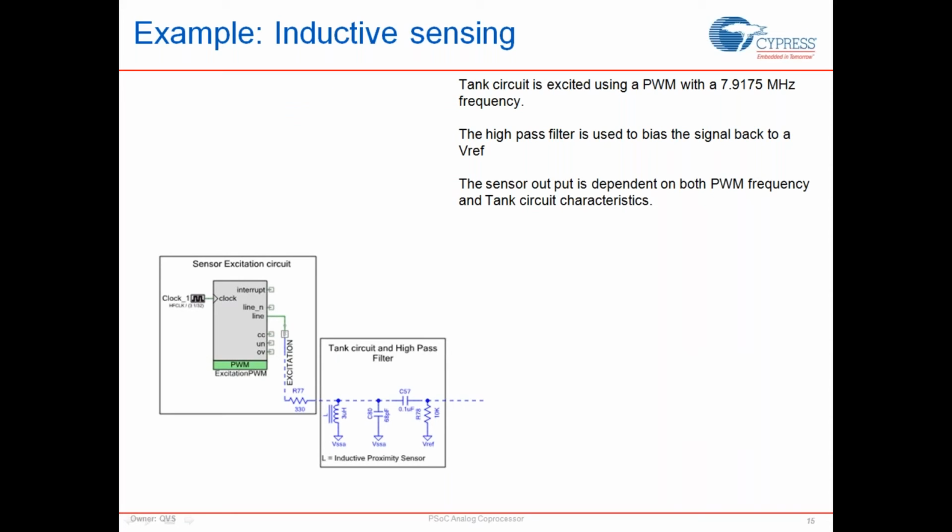And the reason I'm doing that is because I want to make sure that the frequency I'm using to excite the circuit is somewhere on the slope and not at the peak. The reason is you want a linear response at the output when I move the resonant frequency around. If I'm at the peak, the slightest variations would not cause a huge variation in amplitude.